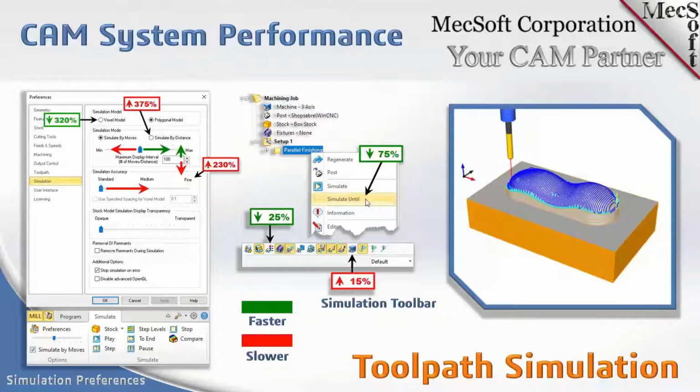So these are dots on the screen, but they also have a Z depth associated with them. We call them voxels, similar to pixels. You can think of a voxel model as nothing but a volume model that we create of a part file or a stock file. And that's what we use for simulation.